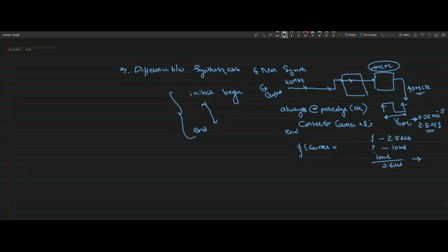Four milliseconds. Not millisecond. So it is actually 2.5 by 10 is 4 into 10 power minus 3 into 10 power 6. So 4 into 10 power 3, correct? So that is 4000. 4000 is the count which is required, right? Now, whenever my count is 4000, it means it actually reached 10 milliseconds, right? Now I got to know whenever count is 4000, my count is 10 milliseconds.